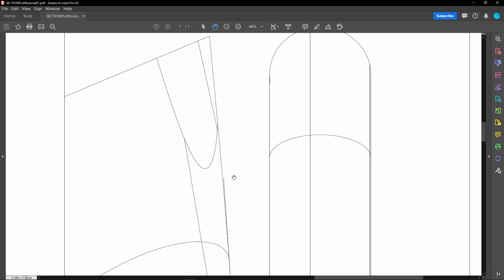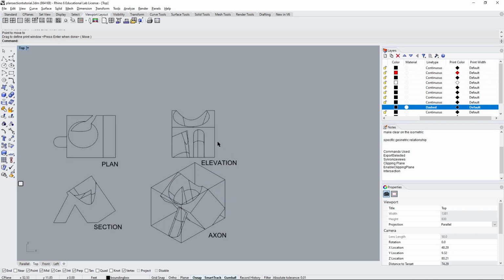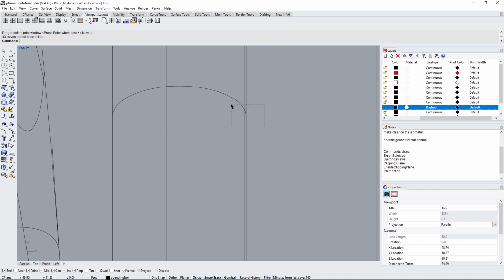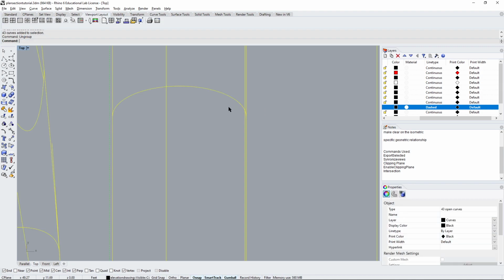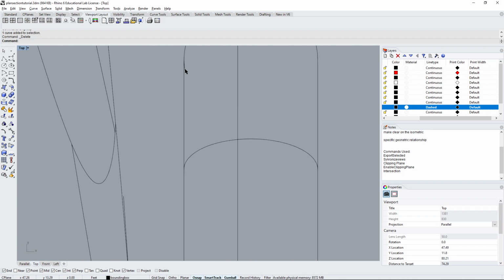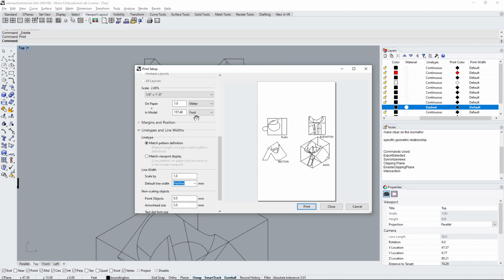This is totally part of the drawing process in Rhino. Now, it took you 2 seconds to print out this sheet, so you can go ahead and go back to your Rhino, zoom in, delete the pieces. You might have to ungroup it if you grouped it like I did. Delete the pieces that you don't want, such as this line, such as this scraggly line, and simply repeat the process of printing it, replace it, and update it.